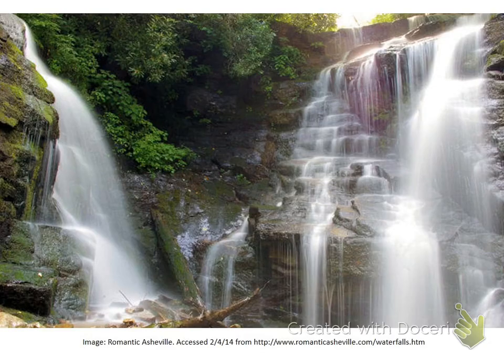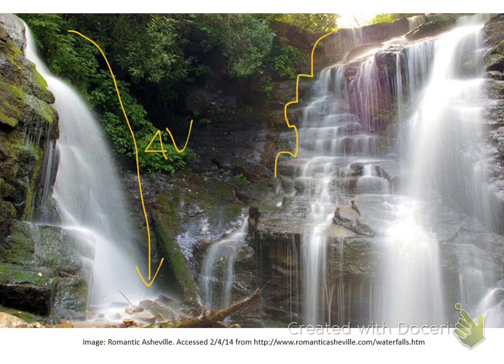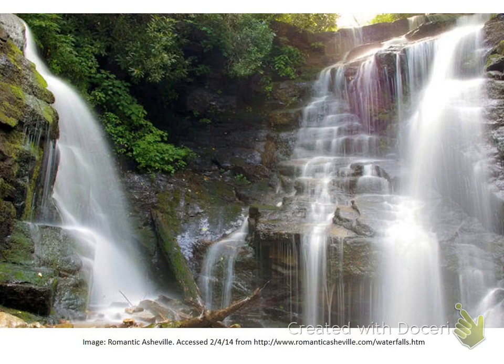And a lot of times you're going to face resistors that are arranged somewhat in series and somewhat in parallel. On one branch, maybe you have one resistor, and you drop the entire voltage over that. On another branch, maybe you've got a series of steps, and you've got a bunch of little voltage drops as you go. In these cases, break it down little bit by little bit, making it simpler as you go.